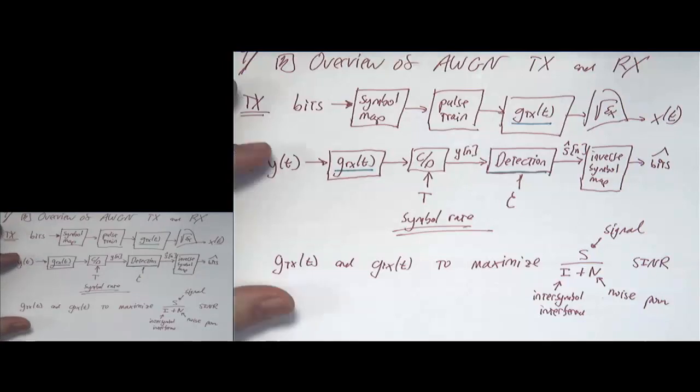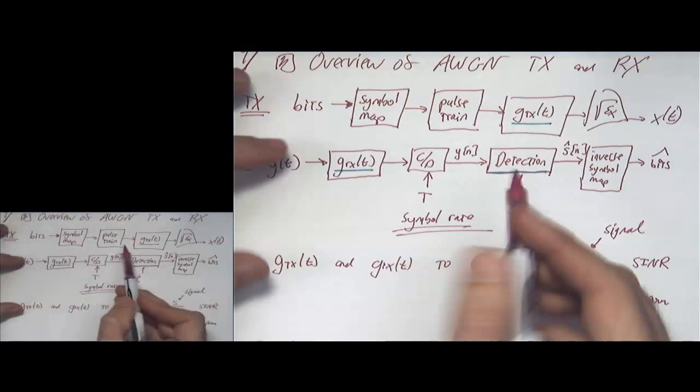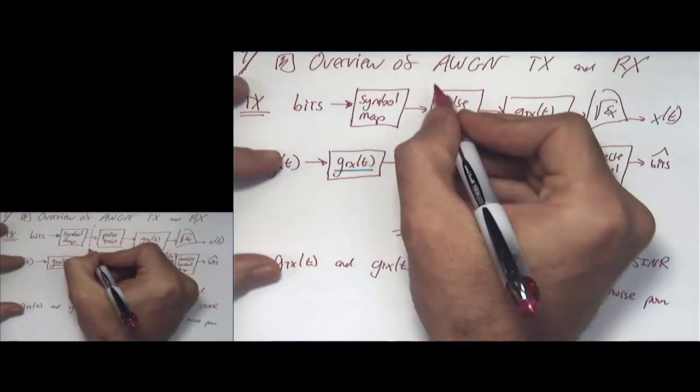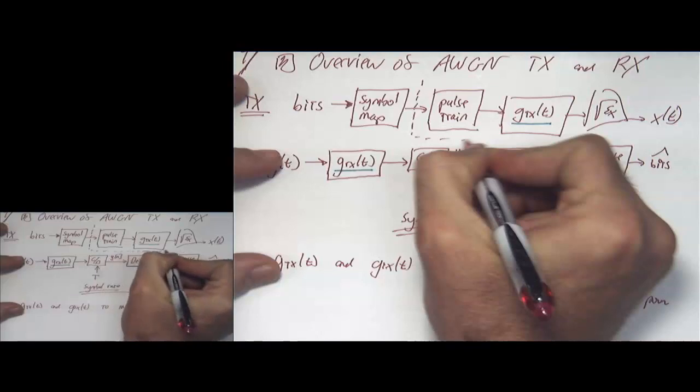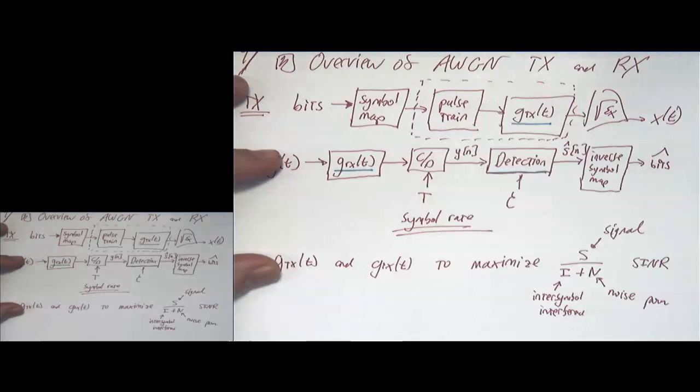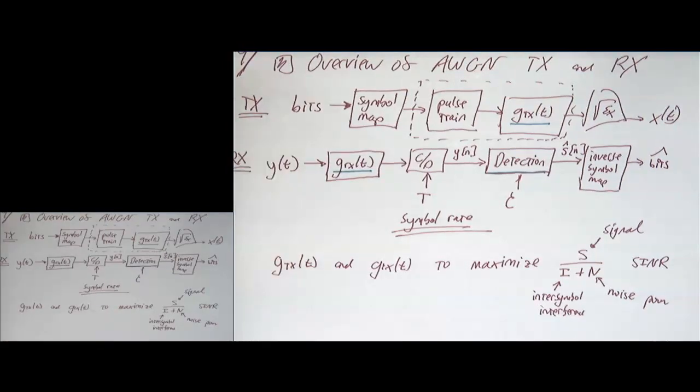And by how to implement, what I mean is that we're going to look at how we can get rid of this block here and replace this with something that involves a discrete to continuous converter or a digital to analog converter, because this right here doesn't correspond to anything we can build in the circuit. So we're going to essentially show how we can do this with digital filtering and a discrete to continuous converter.